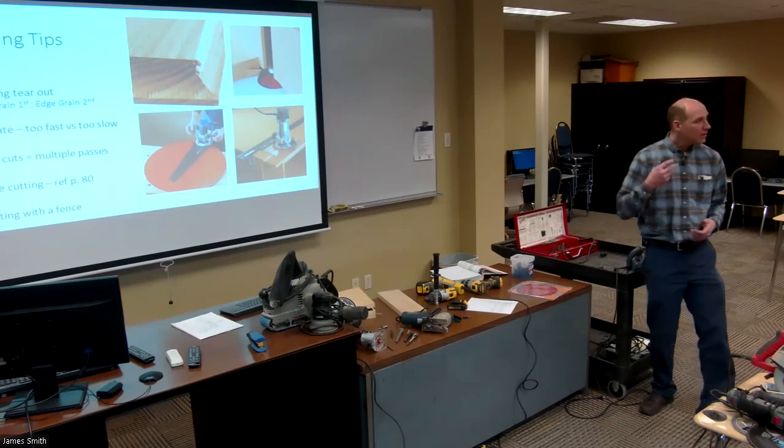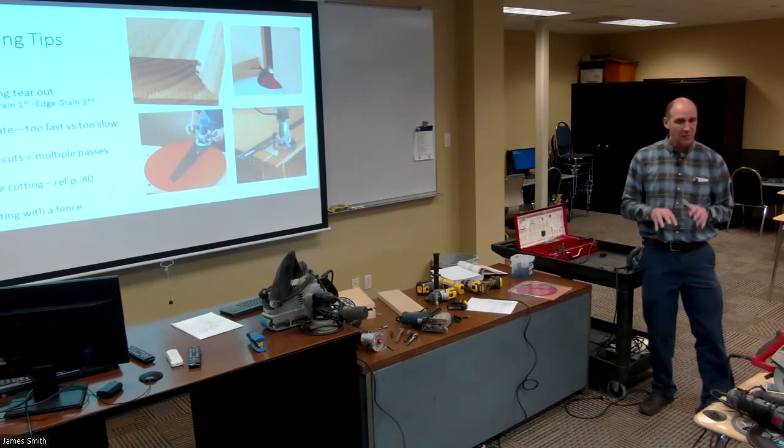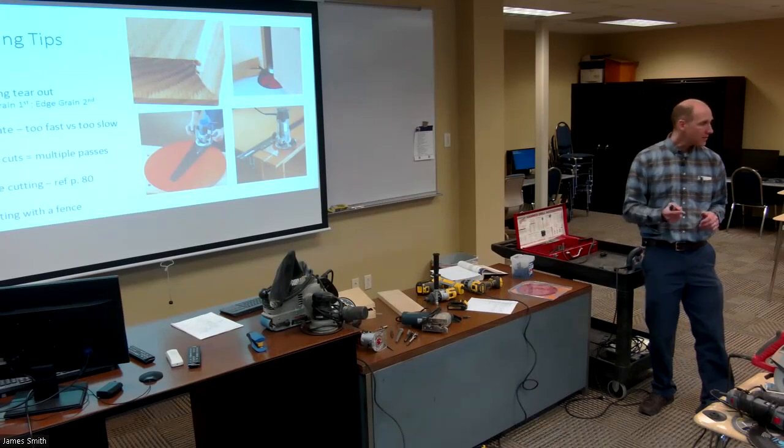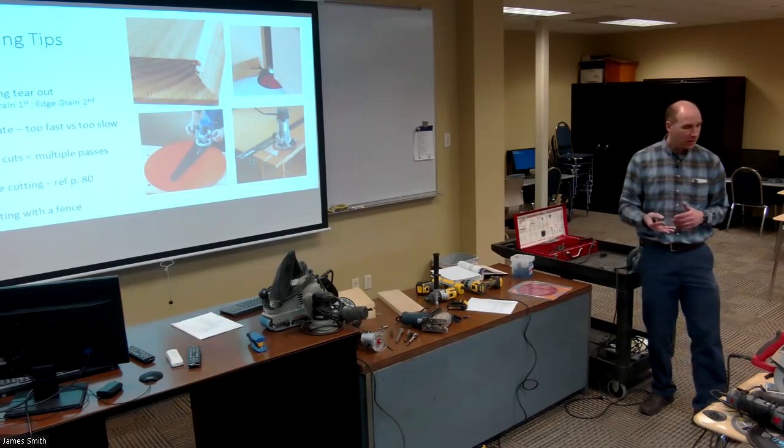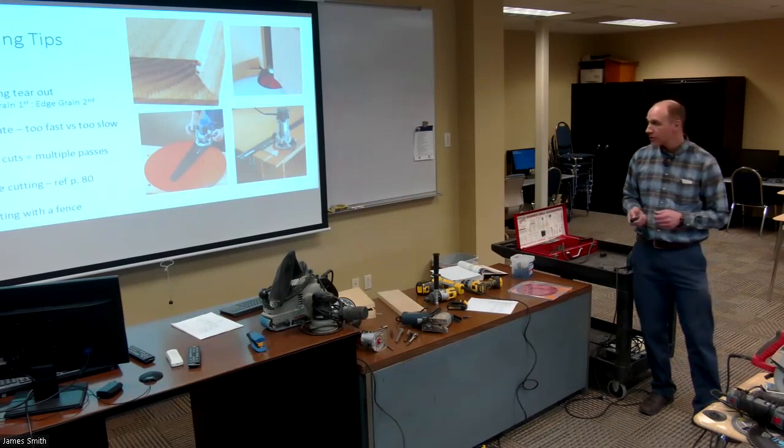Deep cuts, try to take it easy, okay? Do it in multiple passes, all right? Rather than making one deep cut, make a couple of shallower cuts, so that you get a good quality cut, but then you also don't overwork your router so that you don't burn up the motor that way.